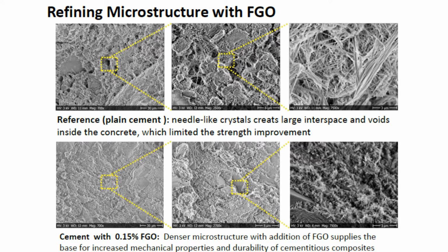So the graphene surface, or functionalized graphene oxide surface, is not only acting as a potential site for nucleation so that the cement hydrate crystals start growing, and that helps in further crystal growth, and there's good bonding by virtue of covalent or hydrogen bonding interaction, but also there is densification. So these multiple effects, I strongly believe, lead to significant enhancement in the flexural modulus, tensile strength, and this kind of mechanical property of the cementitious material. And one thing is very evident: FGO is much more effective than GO as well as the conventional silica nanoparticle as inorganic nanofiller.